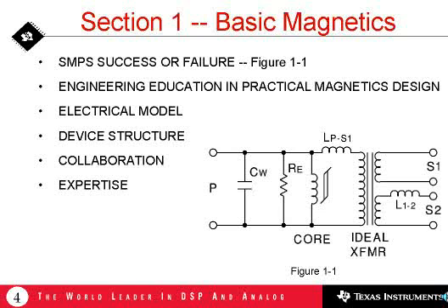There is a topic in the reference section of the Magnetic Design Handbook entitled Deriving the Equivalent Electrical Circuit from the Magnetic Device Physical Properties. This topic will show you not only how to develop the equivalent circuit with the proper location of the parasitic elements based on the device structure, but can also crudely quantify the values of these parasitic elements. Armed with this knowledge, you can go to your magnetic designer and say, Charlie, why don't you change the sequence of those 2 secondaries, and this will put the leakage inductance in a more favorable location.